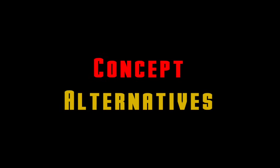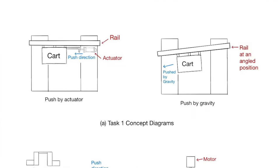Let's talk about the concept alternatives that went into this overall design. So for task 1, launching the device, we had two main mechanisms, as you can see here. You can push the rail slides via an actuator so that you're actually applying a force to the rails, or you can instead tilt the rails at an angle so that simply releasing the rails will trigger the device.